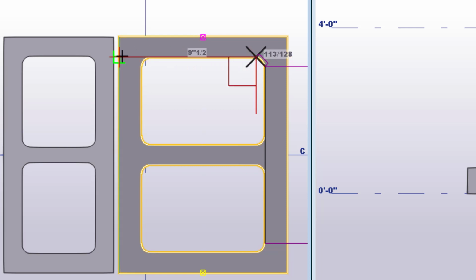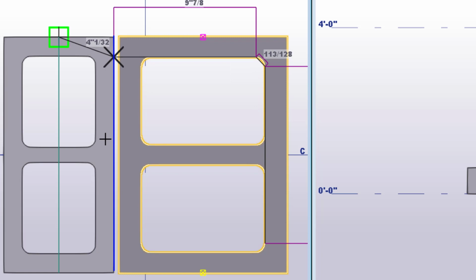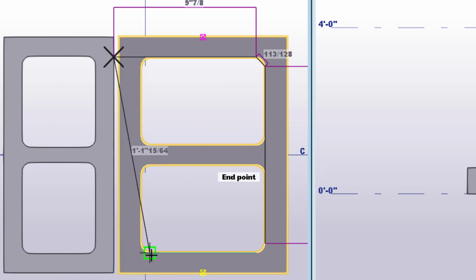The only other thing to keep in mind is that you want to snap to the inside of the block wall on faces which you want to keep, and you want to snap to the outside of them for the ones you want to remove. You can even go so far as to use the face of the other block as shown on screen to ensure that you don't misclick and get any elements of the block face that remain after the cut is applied. Once you complete the polygon, the block is now cut.